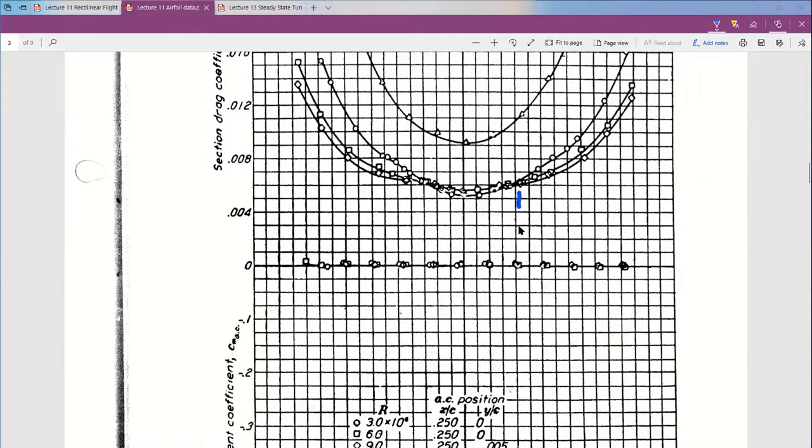So we read up at our CL value of 0.43. Circles are here. Squares are here. So we get a number about something. What's our axis? This one's kind of tricky. So this line is 004. This is 008, so you have to count 004, 005. So this is 006 is that line. Go across. This is 007 up at the next line, so this is 0.0062 maybe.